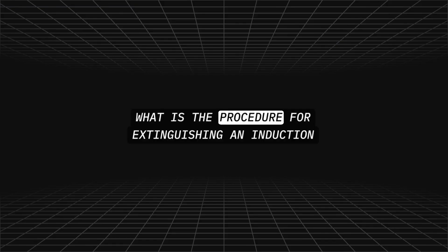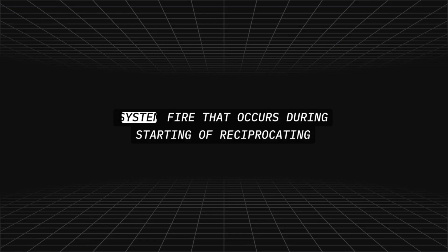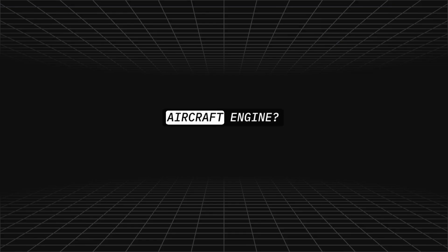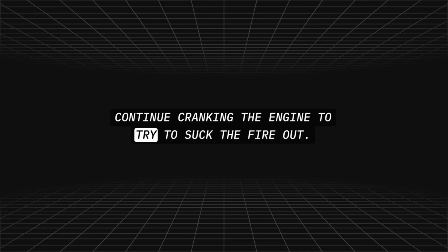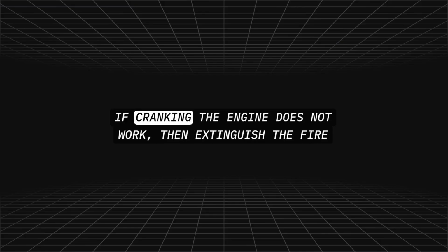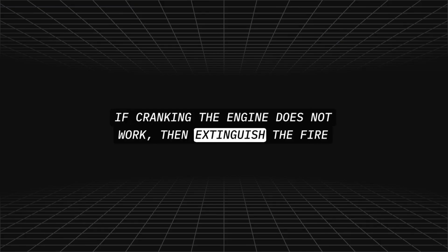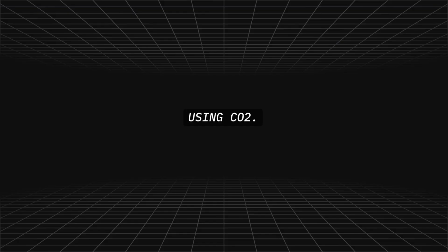What is the procedure for extinguishing an induction system fire that occurs during starting of a reciprocating aircraft engine? Continue cranking the engine to try to suck the fire out. If cranking the engine does not work, then extinguish the fire using CO2.